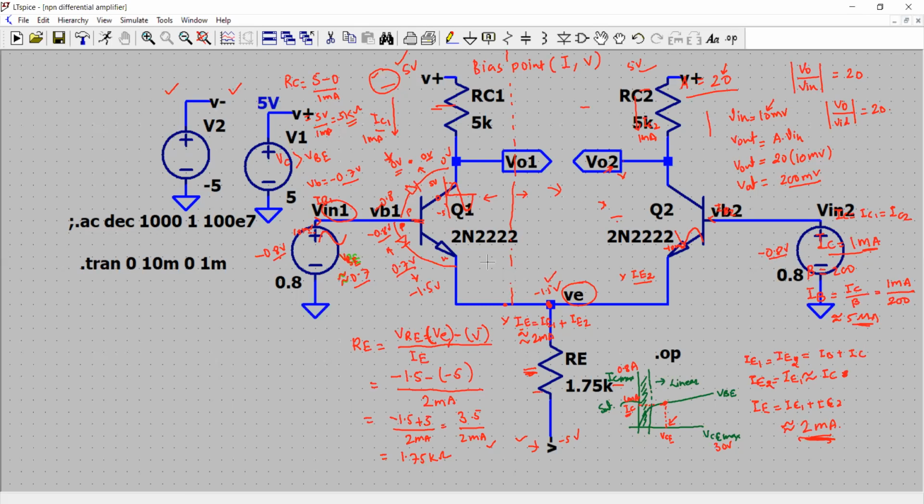Now, we are expecting that with such DC biasing levels and calculations, our transistor circuit, the differential amplifier, will always be in active region, and we'll have a linear amplification of the applied signal. Now, on this DC voltage level, which is the 0.8 at the inputs, let me draw it here. So you have 0 volts for the input signals, and let's say somewhere here you have my 0.8 actually.